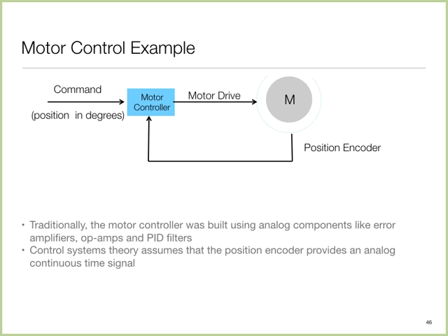That is, the sensor is going to take a sample every time period, and the whole thing runs in a synchronous manner. Every clock tick, we are taking a sensor sample and comparing it against the set point. The set point may change, but perhaps slowly. Usually, these control algorithms are things like PID control or PI control, and nowadays more sophisticated model predictive control or even machine learning algorithms of various forms, like the reinforcement learning that Sandeep described. But that's normally what goes on.